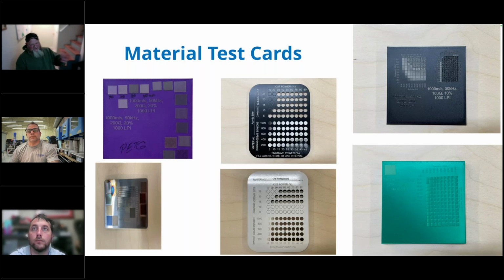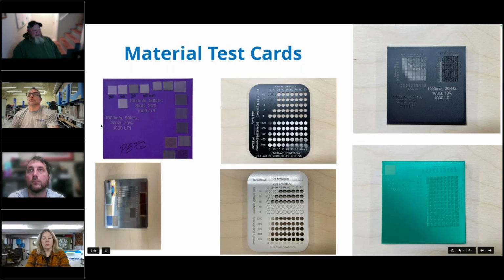Once I get a rough area of where I'm wanting to shoot for, I start making little 5 or 10 millimeter squares, and then run specific settings to get those squares to do what I want.